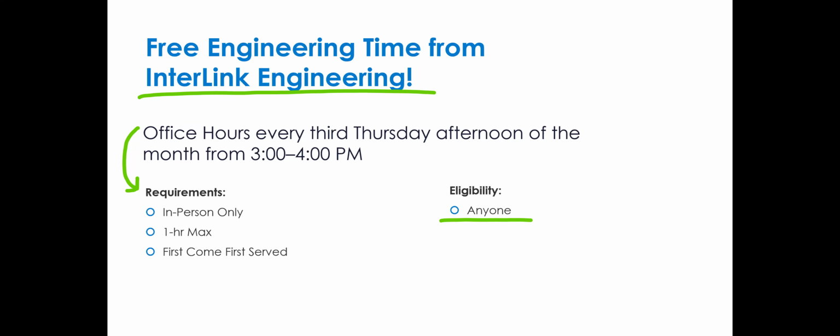For machining, you can get away with adding additional ribbing without all the necessary drafting and everything else. However, you do have to consider increasing thickness as well. When doing that, the added features that you incorporate should accommodate a lot of the DFM considerations that I mentioned.